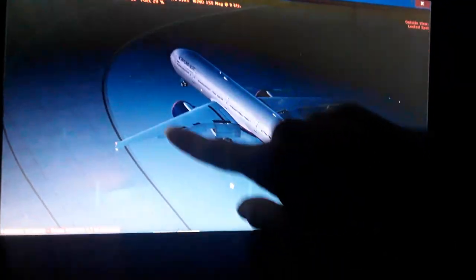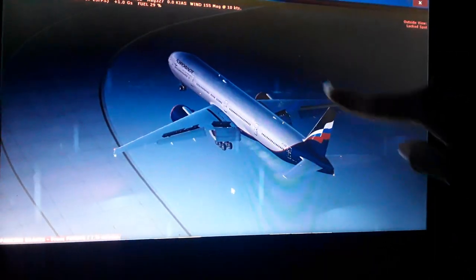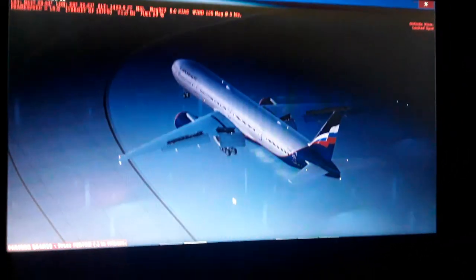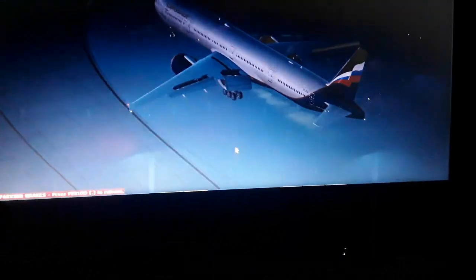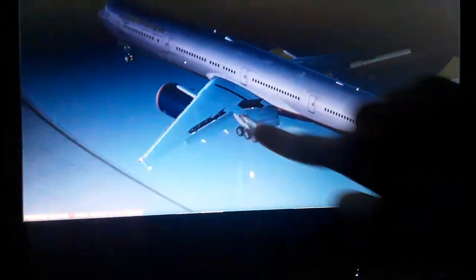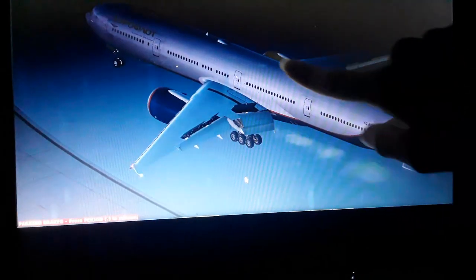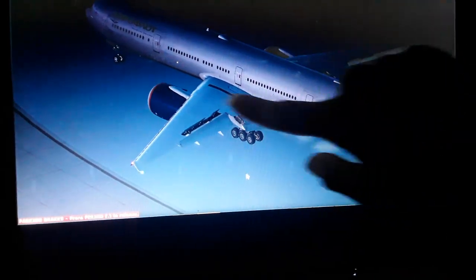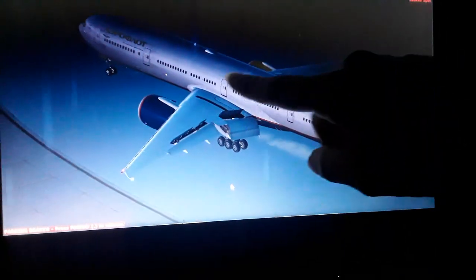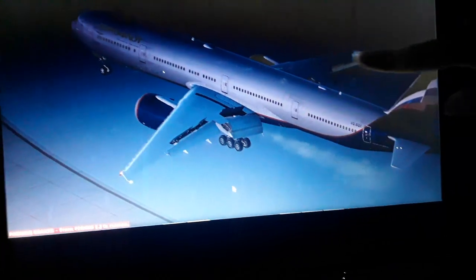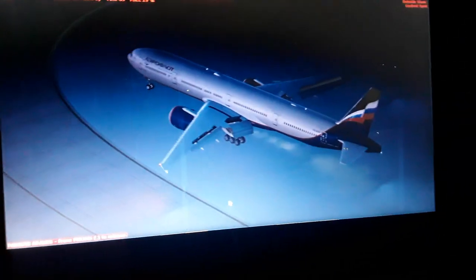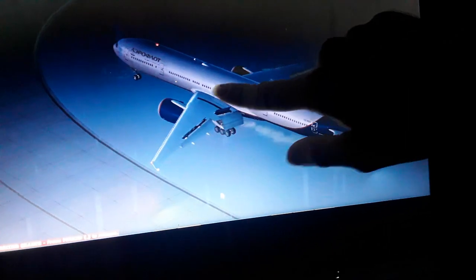So you can see here the wings of the aircraft. They hold the weight of the aircraft when the aircraft is airborne, when we are flying. You can see we have the vectors from the engine that propels the aircraft forward. The thrust overcomes the static and kinetic friction, and the lift from the wings overcomes the weight of the aircraft. Also, you can see the aerodynamic center position, which is about 25% of the chord. This is the position where the maximum aerodynamic lift occurs on the wings.